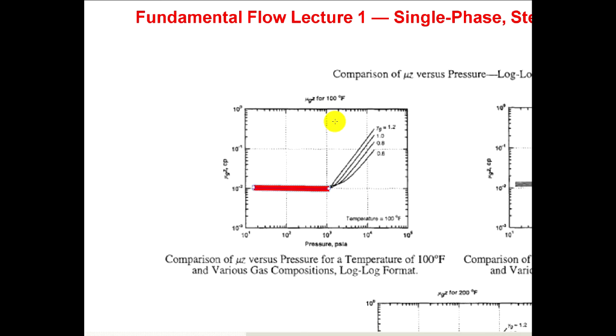This was a big conclusion in Ramey and Wattenbarger, right? That for pressures less than 2000 psi, the pressure squared method was sufficiently accurate. Why is this important? Because if you can use pressure squared as your pressure variable, then you don't have to calculate pseudopressure, which is a big savings. You don't have to carry around a bunch of things that you don't know what they are.